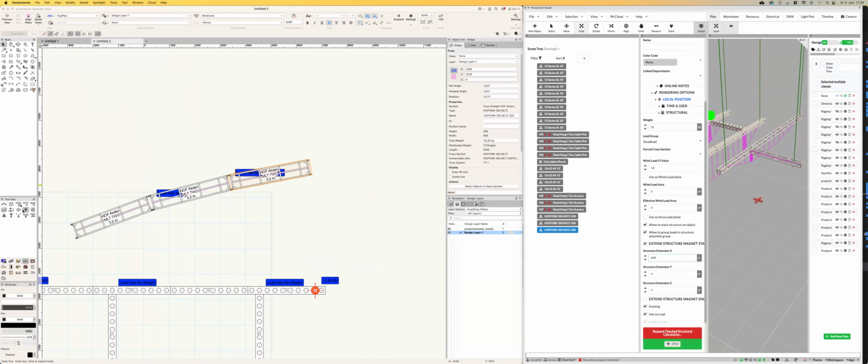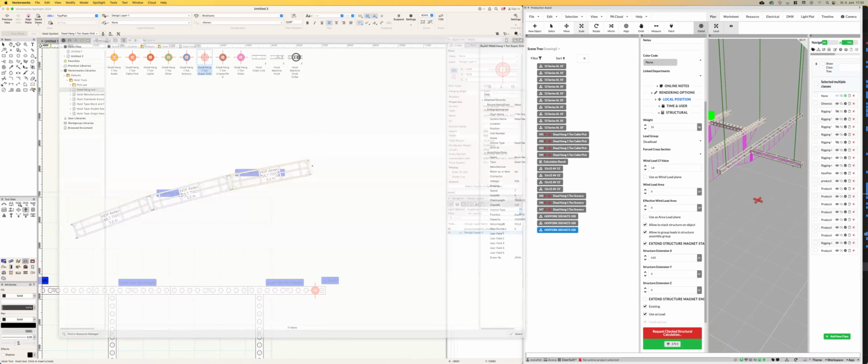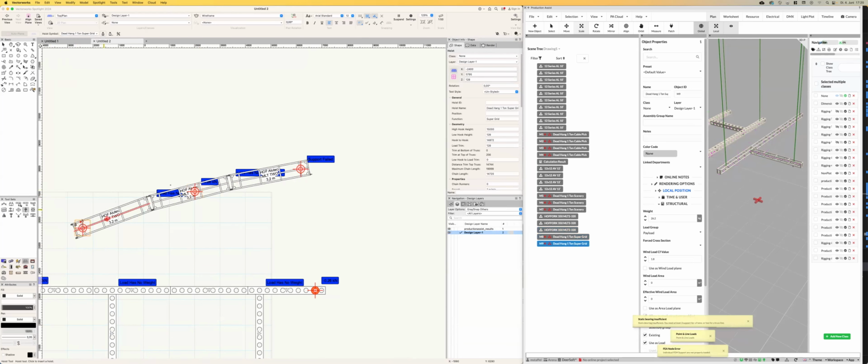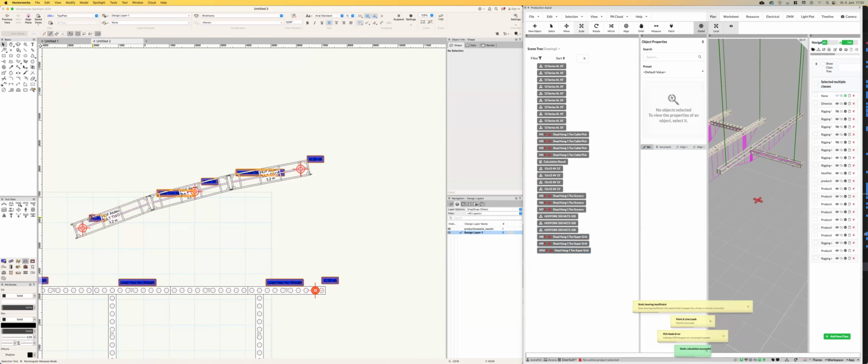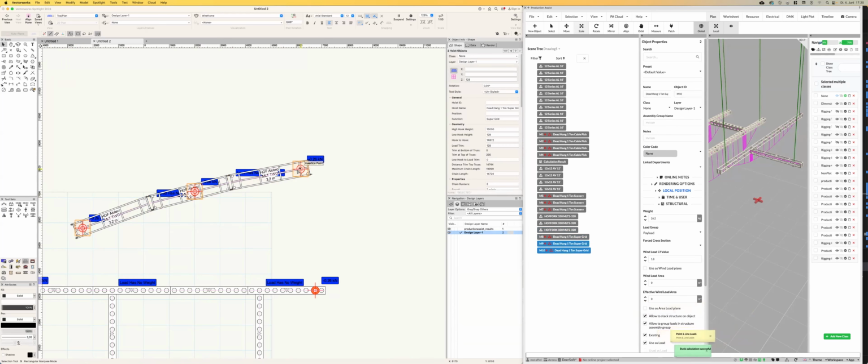If you then go into this and add somewhere a hoist, so 1, 2, 3 in here, you will see out of the box, this will calculate and actually give you a calculation result, even for the curve structures, without doing anything. For the bending moment in here, the MLT truss can take bending moments in different directions with a different height. So if you're bending it up, it can take a different load than when you're bending it down.